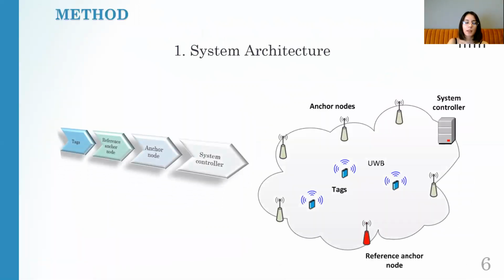In the localization system, the main components of the system consist of tag and anchor devices. The tag is the mobile device whose location will be calculated, and the anchor is the fixed device that calculates the location. A tag sends the signal to the anchors using ultra-wideband technology. The location data of the UWB signal detected by anchor is calculated with necessary mathematical operations in the device, and this data is sent to the server via the wireless network.